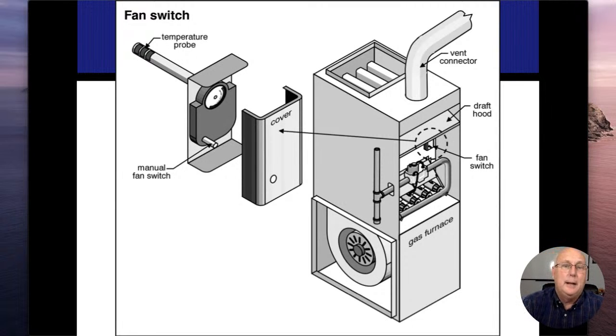All right. I talk about that temperature rise that we measure with those turkey thermometers or little dial thermometers, and this area up here, the ductwork that would be there, that would be called the plenum, and this is the area that I usually take those measurements.